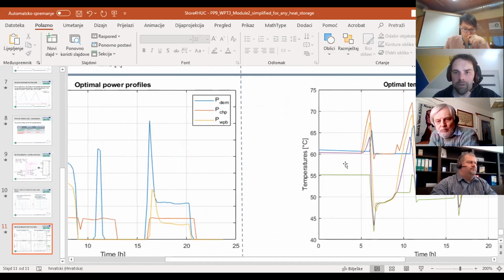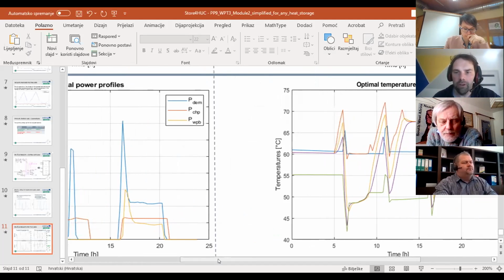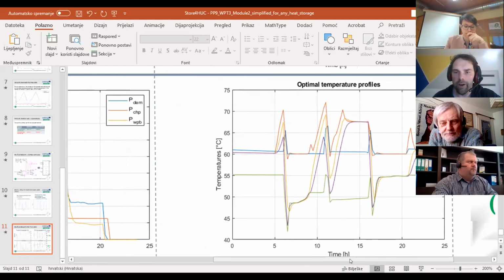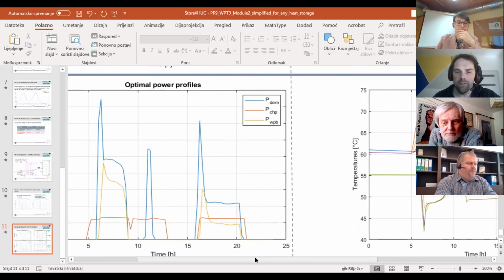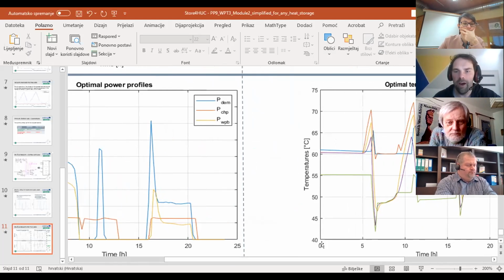It's 65. Okay. Yeah. So whenever the temperature in layer T4 rises above 65 degrees, you can no longer use CHP. And you see that you strive with your optimization to run the system in a way that whenever the heat is needed, you engage the CHP and you have your temperature in layer 4 reduced to a proper level that enables your CHP to run.